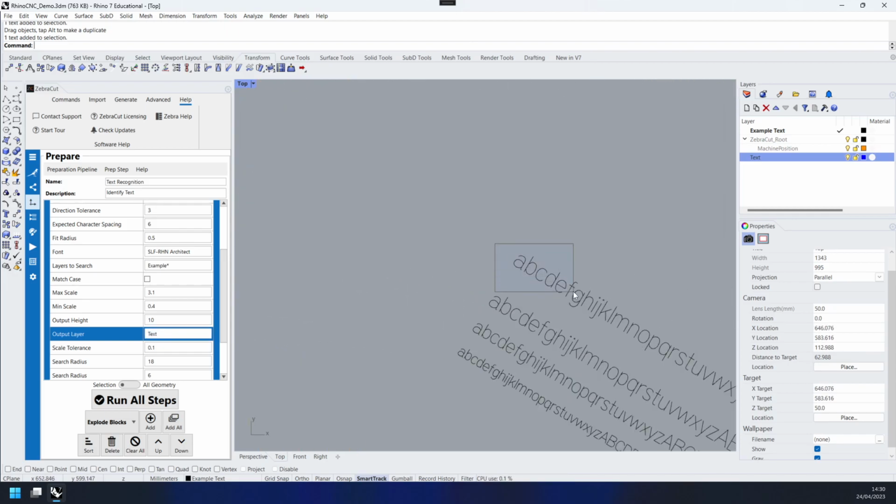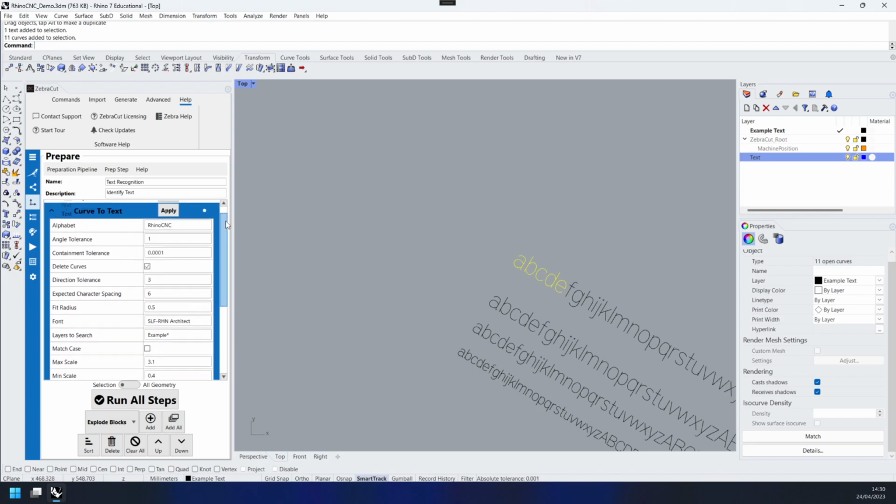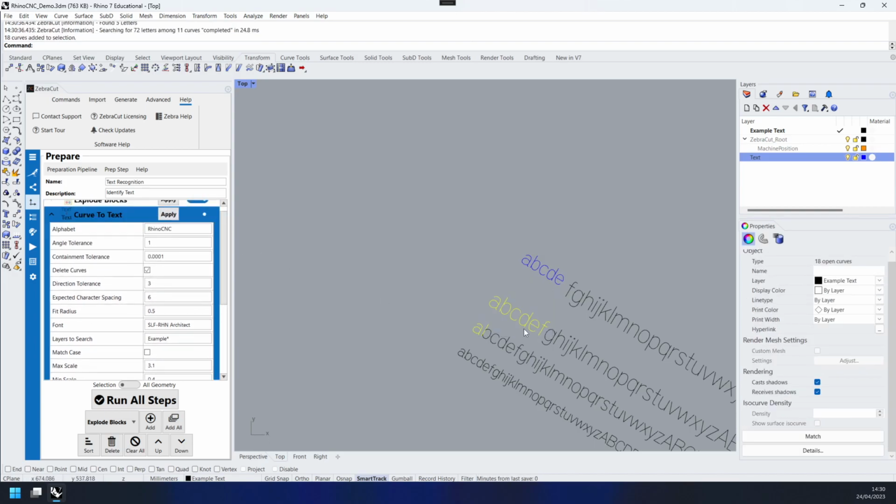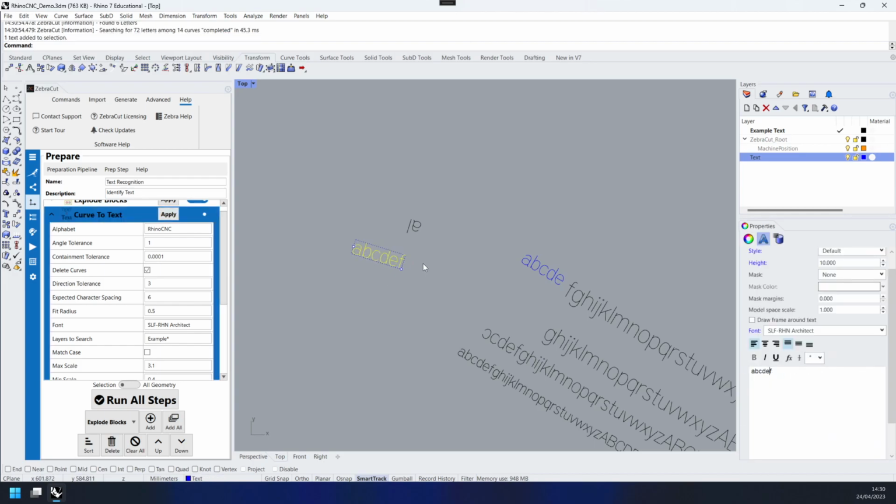Now it's worth saying that Rhino does sometimes try to reverse your text. So if I take this piece of text here, and if I just rotate that and make it point the other way, now I've configured my Rhino so actually it won't, when I have my text in this direction, because it's just curves, you can see it's backwards. However, when I go and recognise it, you'll see it flops the other way around. Now that is actually Rhino itself trying to show you the text the correct way around for you to be able to read it, but in this case the text is actually pointing to the left. That is a setting you can change within Rhino, something to be aware of. You may well want to turn it off if you're working with text regularly, so that you know when text is backwards.